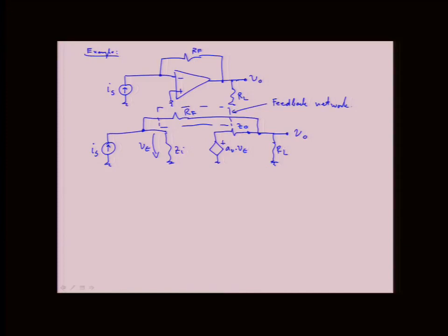Okay, so before we do any transformations of the amplifier, this is obviously a shunt-shunt example. We have the current summation right here from the feedback, and then we're sensing the voltage here from the output. So this is shunt-shunt. But let's first take a look at how this RF resistor maps to the Y parameters of the two-port network, and how complicated a two-port becomes for a simple resistor like this.